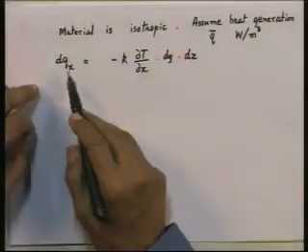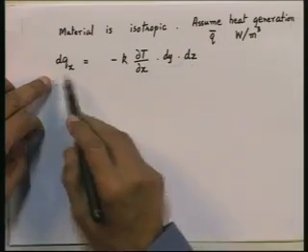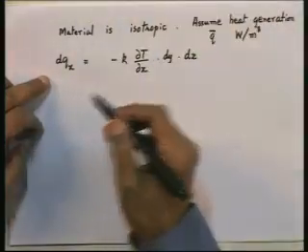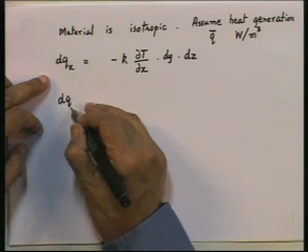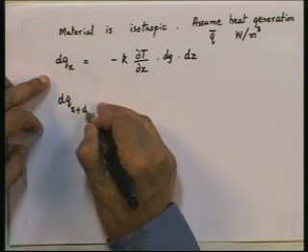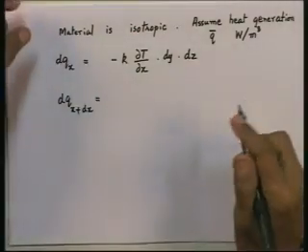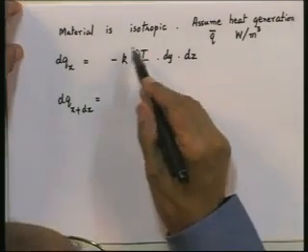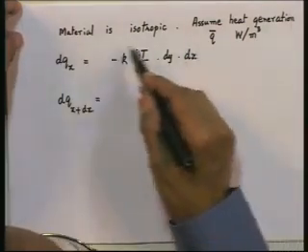Now, let us go back to where we stopped. Fourier's law tells us the rate at which heat flows in the x direction. So, dqx is this. If I move a distance dx forward in the x direction, then I will get the expression for dqx plus dx. Now, we ask ourselves in this earlier expression, what are the quantities that may vary in the x direction?